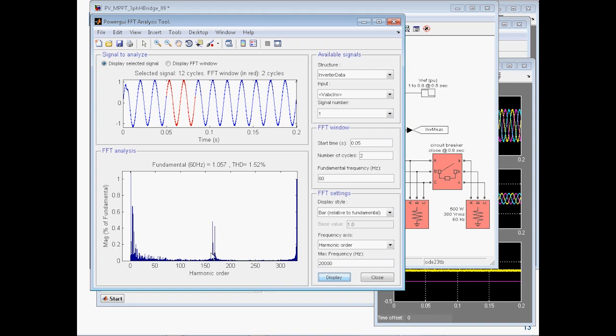The reason you're seeing these harmonics makes sense, because I'm producing 60 hertz and using a 10 kilohertz PWM frequency. 10 kilohertz is about 166 times 60. So that's why you're seeing the 166th harmonic and higher orders of that, like twice that over here. That's one of the reasons why some people use higher order converters. The more devices you put in, the farther up you push these higher order harmonics, and the cleaner your overall signal is going to be.